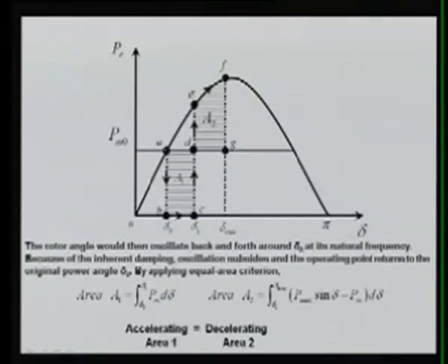This PM here, A was your operating point, because your PE here is equal to your PM naught, that is the PM naught that you are getting. So suddenly there is a fault. So what is happening? Your PE becomes 0. So this is suddenly coming to this point, and then till the fault is persisting, here it is going, and at delta 1, once the fault is cleared, again it is going back to the PE. Again the PE is going to be delivered to the infinite bus.